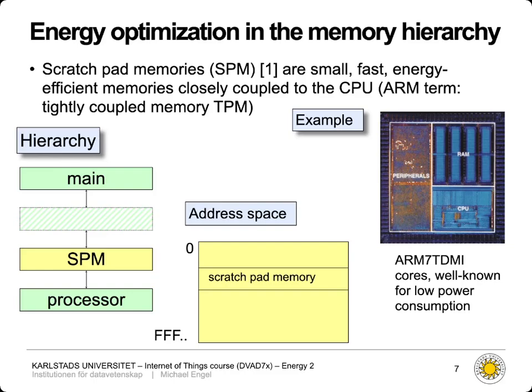They are what we call static RAMs. So static RAMs actually don't need refresh because they keep their contents due to the circuit technology used to create them. But unfortunately, this circuit technology is much more space intensive than the one for DRAMs. So a static RAM or SRAM usually uses 6 or 8 transistors to implement a single bit memory cell, whereas in a dynamic RAM you only use one transistor and a small capacitor.